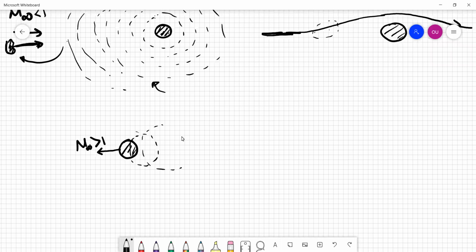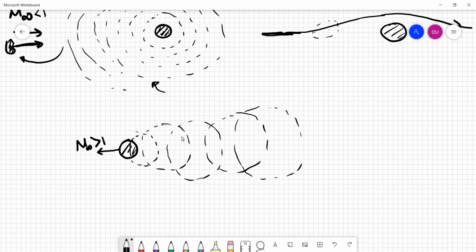So all the waves that it generates, it is moving faster than any of them. So it will keep these waves behind, okay? These disturbance waves that are propagating with the speed of sound will form what we call a Mach cone around this body. So this is the boundary of this wave, this is the boundary of this wave. Of course, you can imagine we have probably millions of waves here.